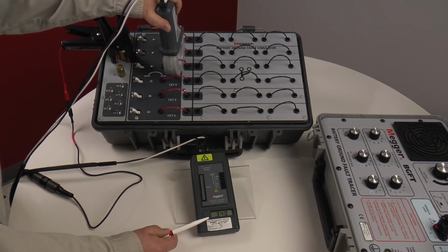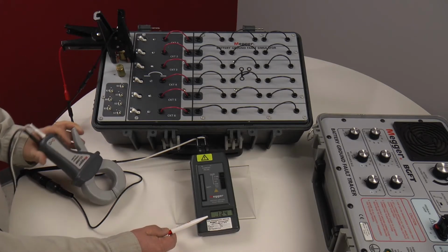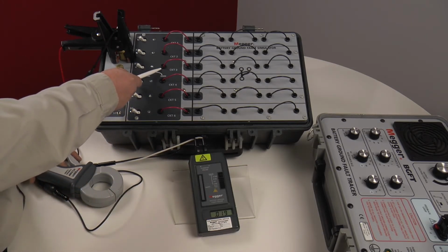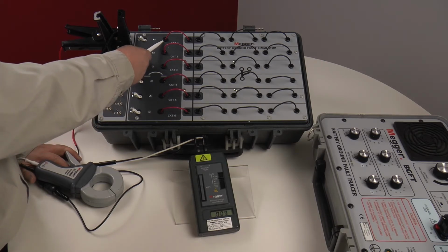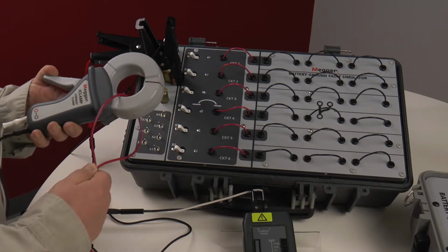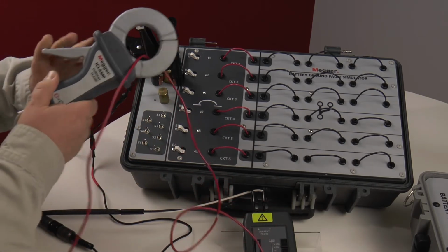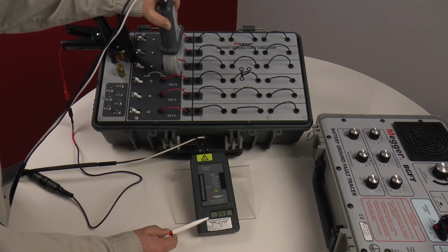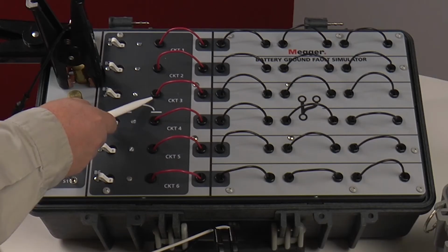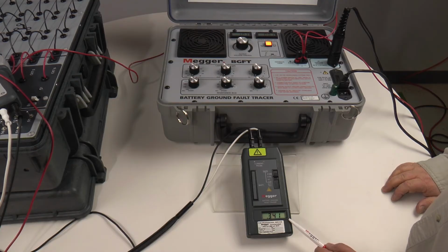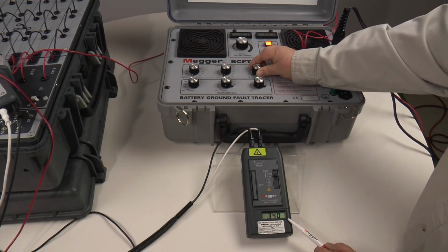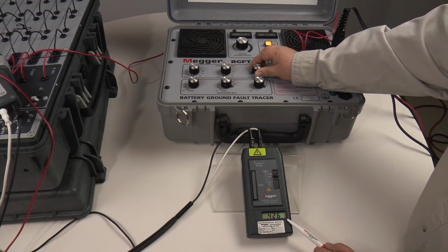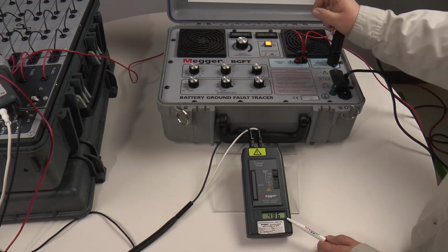However, from our initial characterization, we know there is a lot of leakage current on the system. So now we need to determine which circuit has the resistive fault and which one has the phantom fault due to leakage current. To do this, we are going to reinstall our feedback loop. Now, we are going to see if the fault current on circuit 3 is capacitive or resistive. Circuits with high capacitance have high leakage currents, so we start turning the capacitance on our Wheatstone bridge.